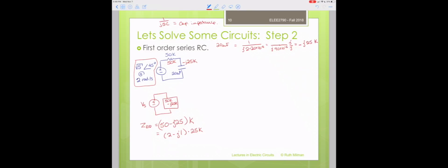And the impedance in Cartesian format is useful and critical information, but it would be much more convenient for us if we actually had this impedance in polar coordinate form. So we're going to take it and convert it into polar coordinates. How do we do that? Well, the first thing we do is find the magnitude of this. The magnitude of the vector is simply equal to the square root of the real part squared plus the imaginary part squared.